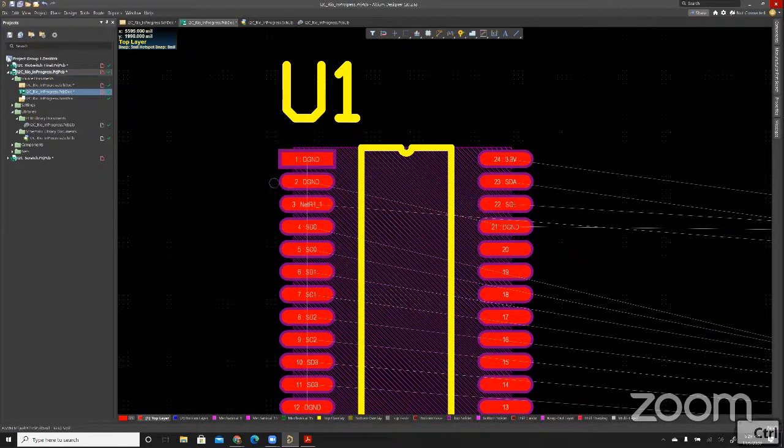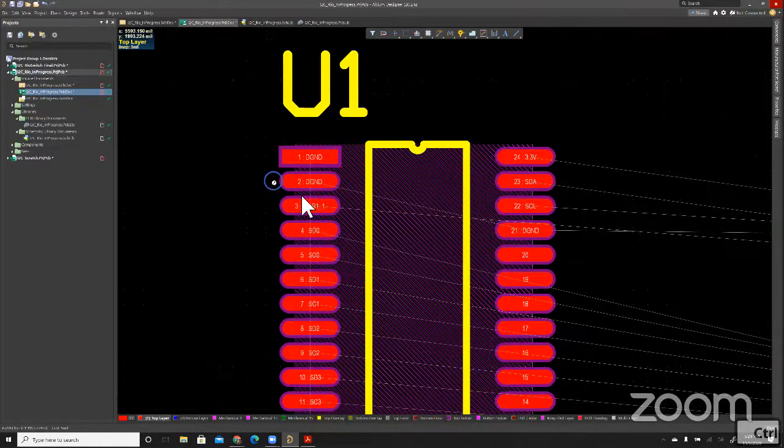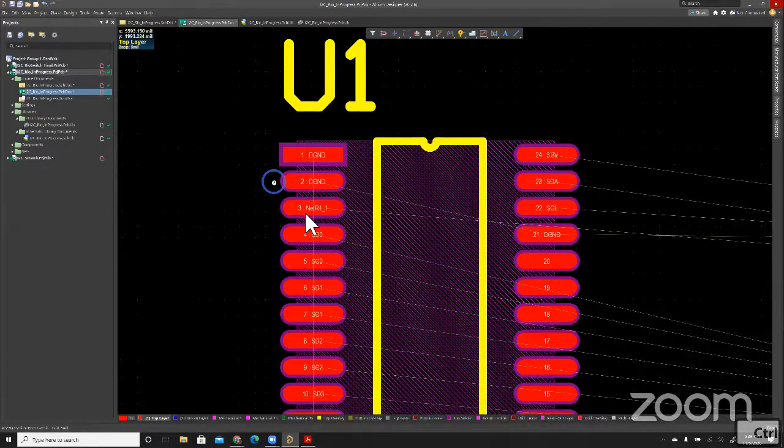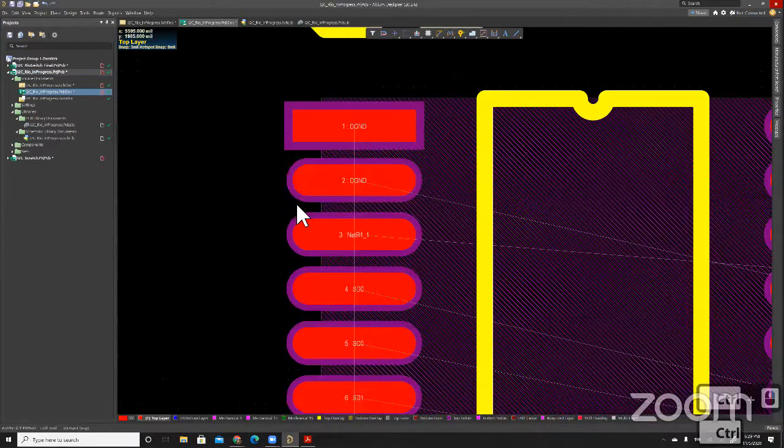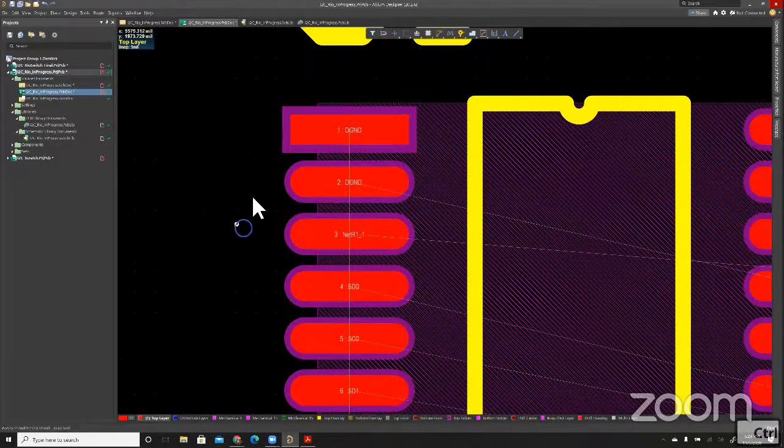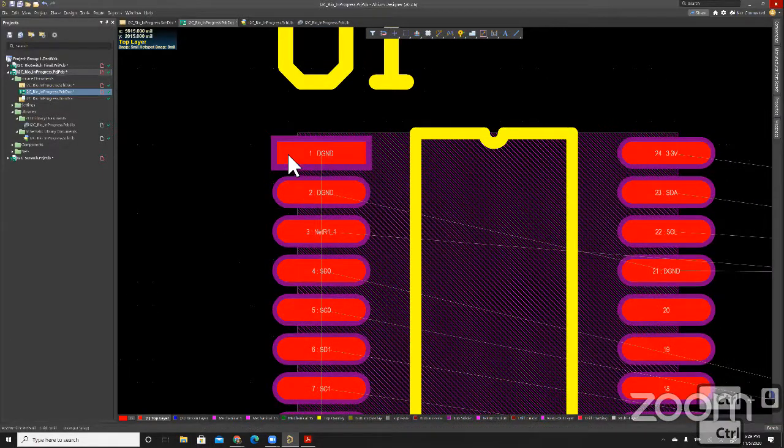So it's usually useful to make sure that you've got a little bit of gap between your top solder masks or bottom solder mask, because that means that covering material will go between here, which means that when you go to solder it, sometimes you can be really sloppy and just put a big glob of solder and then touch the pin with your soldering iron, and the heat will pull the solder into it and remove any solder bridges between pins, because at that point there's nothing for it to connect to down here.